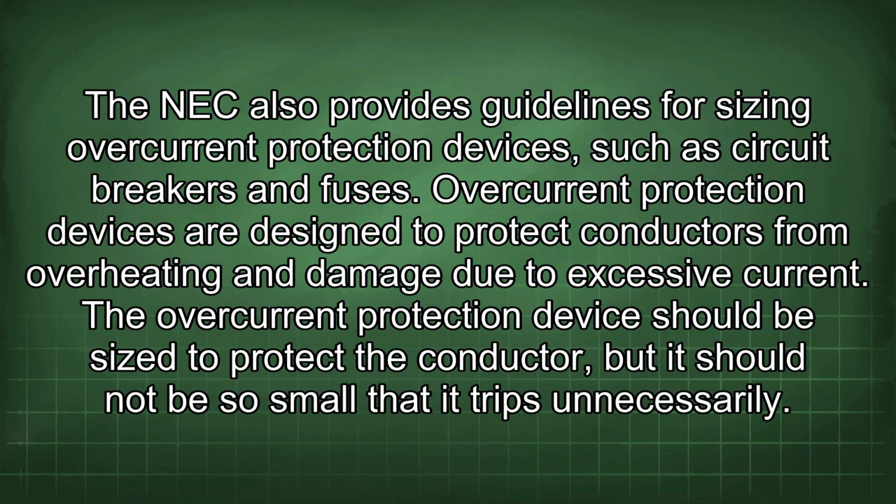The NEC also provides guidelines for sizing overcurrent protection devices, such as circuit breakers and fuses. Overcurrent protection devices are designed to protect conductors from overheating and damage due to excessive current. The overcurrent protection device should be sized to protect the conductor, but it should not be so small that it trips unnecessarily.